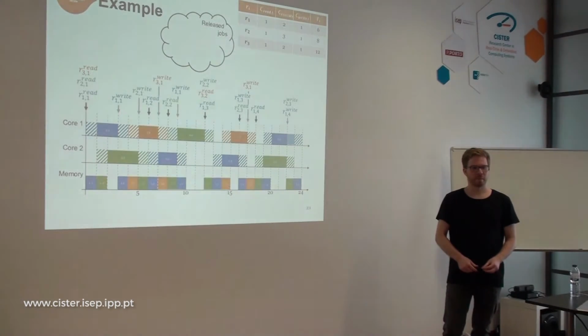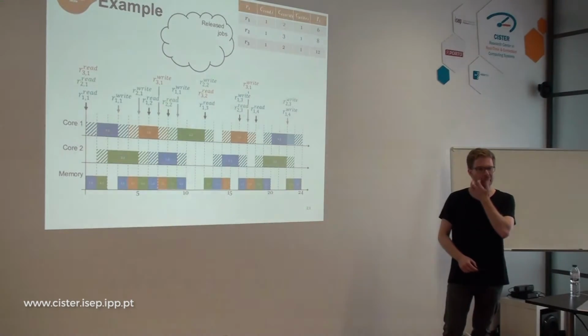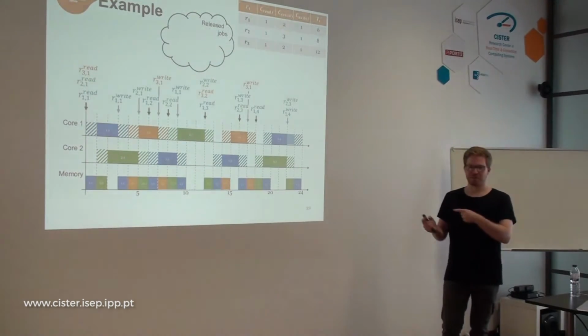And when you use more than 8 cores to run the runnables, basically you don't improve the performance. Yes. Okay, so why not, instead of taking 14 cores to run the runnables and 2 cores that you disable to take 2 label banks, use 8 label banks and 8 cores to run the runnables, and then try to distribute the interference, so map the labels differently across these 8 label banks so that you will reduce the interference.